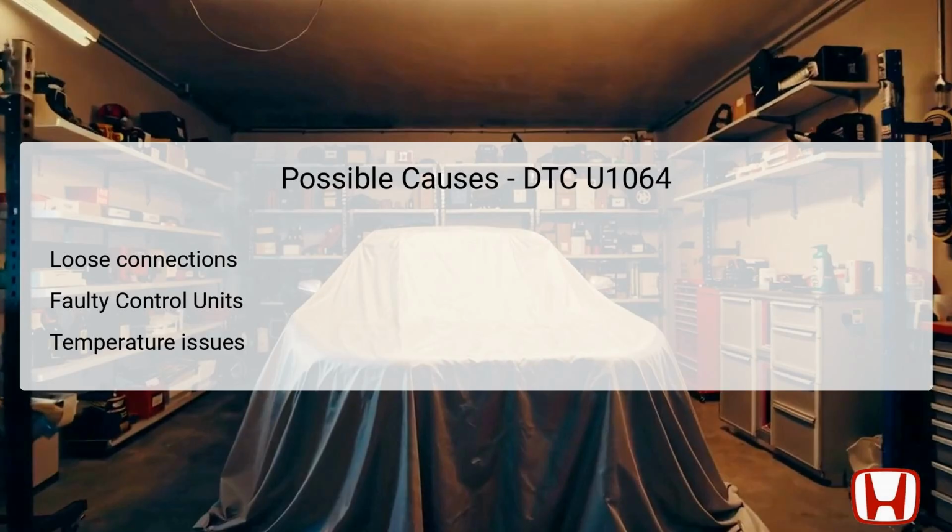Thirdly, if the seat's core temperature exceeds 85 degrees Fahrenheit, the seat heater control unit will not activate, leading to a belief that there is an issue, when in fact, it is operating correctly under these conditions. Understanding these causes is essential to target the right area during troubleshooting and repair.